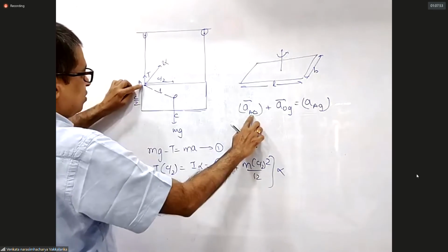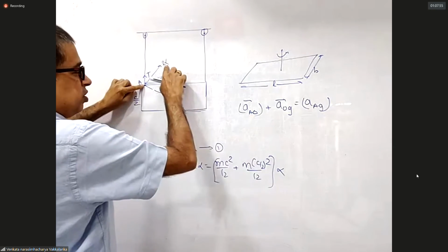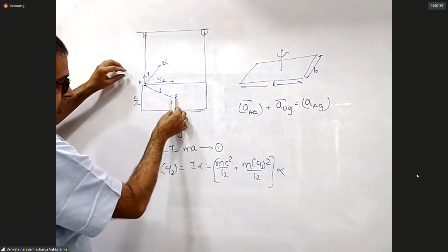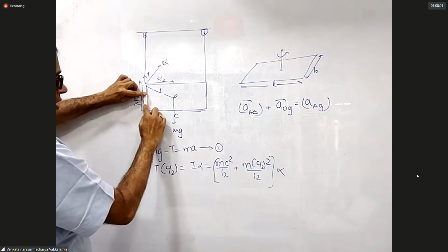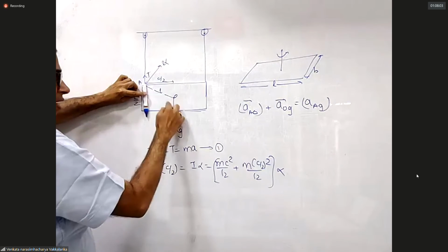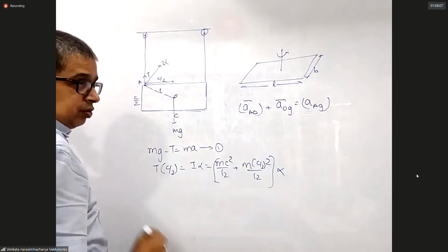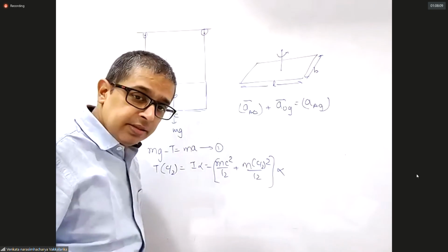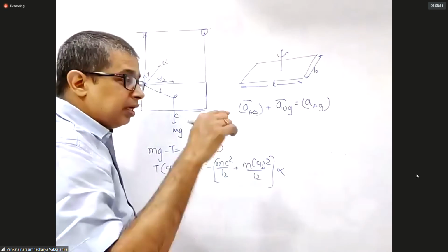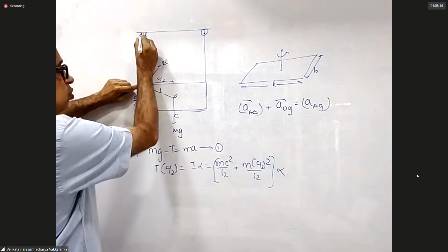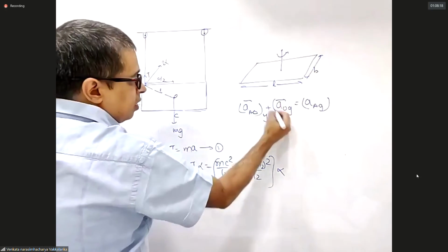The acceleration of A with respect to O is L alpha. The acceleration of O with respect to ground is downwards. That means I will have to resolve the resultant of L alpha along the length of the string and equate it to 0. Agreed? Yes, sir. Instead of taking the resultant and resolving, I will resolve and take the resultant along the y-axis.